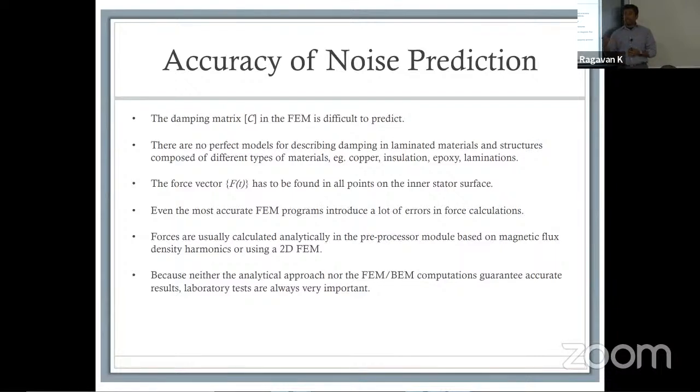A wind tunnel is basically for identifying, once again, you're looking at the frame of the vehicle. You're trying to identify how much noise you're going to generate, what kind of drag you're going to get. That's for the vehicle. So wind tunnels can be hard. The fourth thing I haven't mentioned, which perhaps is important, and several universities do have it but not all, would be a chassis dyno, a place in which you can actually put the vehicle and do all of your vehicle testing and benchmarking, right? So having these four things accessible in transportation research does, in my opinion, give you a substantial benefit or edge in doing your research.